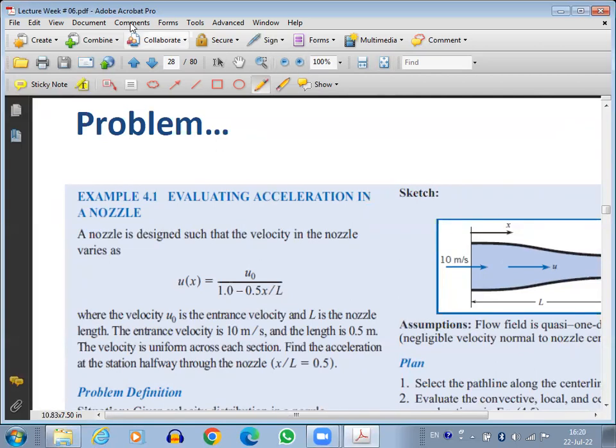So if we were to calculate the acceleration of a fluid in the flow, simultaneously we can have curvature as well as non-curvature. So both of those accelerations can be calculated. Most of the time what we do is we split the problem into multiple parts. The part where there is curvature, we solve it separately. The part where there is no curvature, we solve it separately. But it cannot be a universal problem.